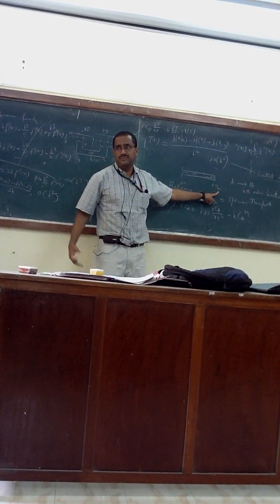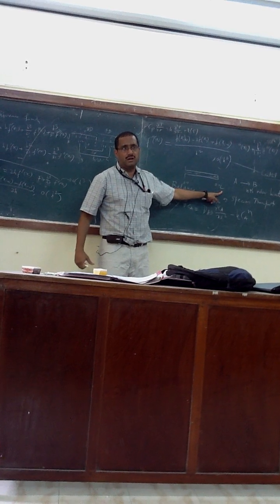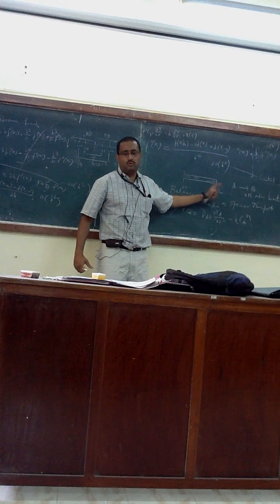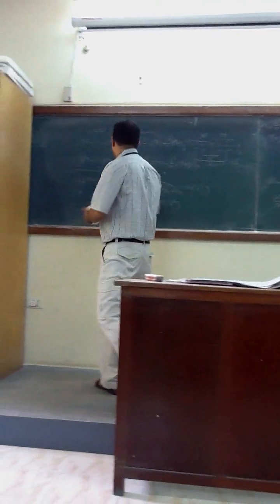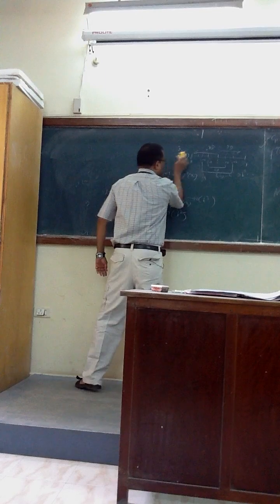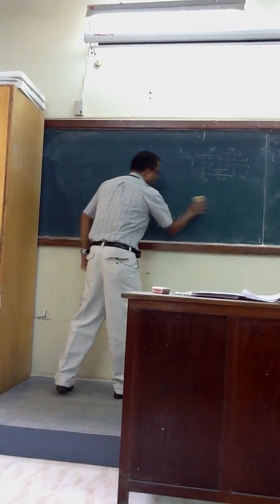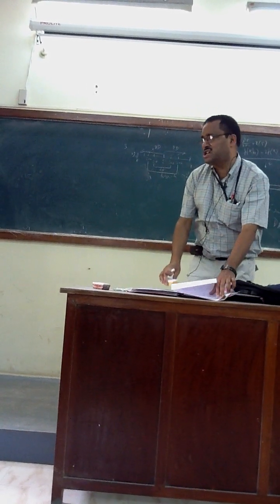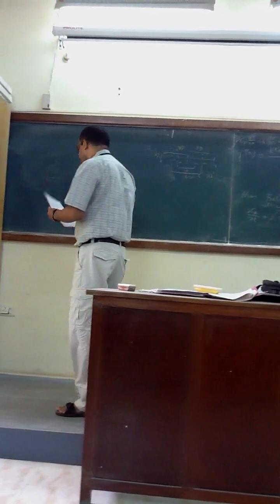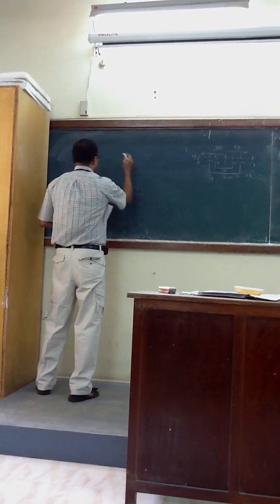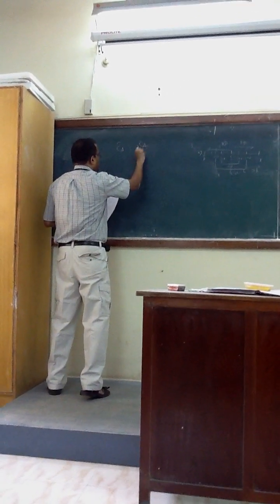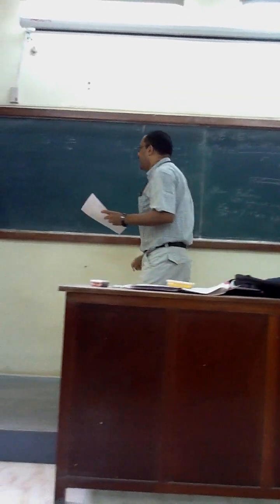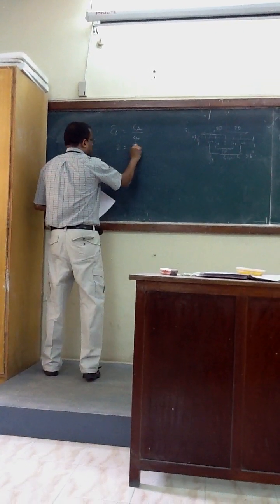L may not be 1. L could be 3 cm, 4 cm. You cannot do the finite difference method because h may be greater than 1, which is a problem. So you need to do dimensional analysis. In a real problem, the length scale is not 0 to 1, and in that case numerical techniques cannot be implemented. It will be a serious problem. In that case, we do it dimensionless. So CA bar we can write as CA by CA0, the difference concentration. Z bar, the dimensionless variable, we define as z by L.